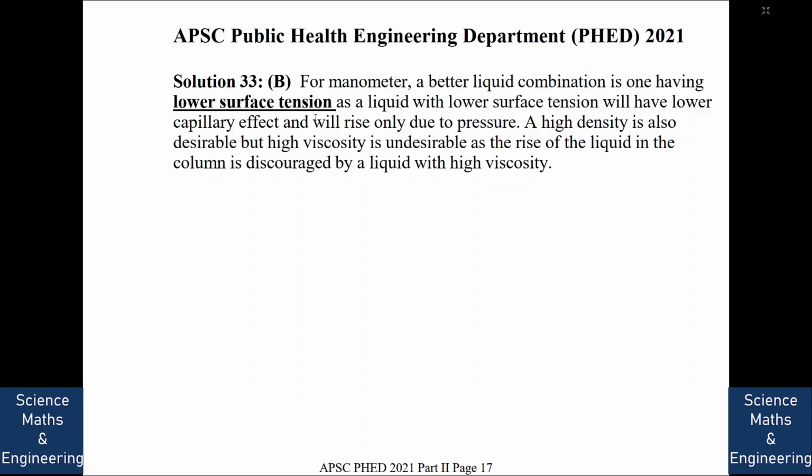of any capillary action. Also, high density fluids are generally desirable, but high viscosity fluids are not desirable, because if a liquid has high viscosity, then it will not rise or fall with the change of the pressure, so not accurately. So we will have a very less sensitive manometer, so we do not require high viscosity. So our answer is low surface tension liquids. So we'll go to the next question.